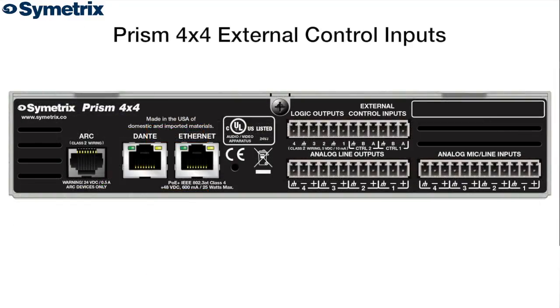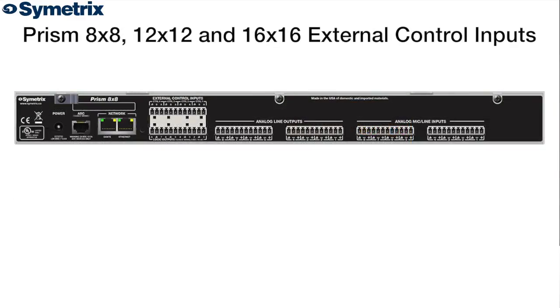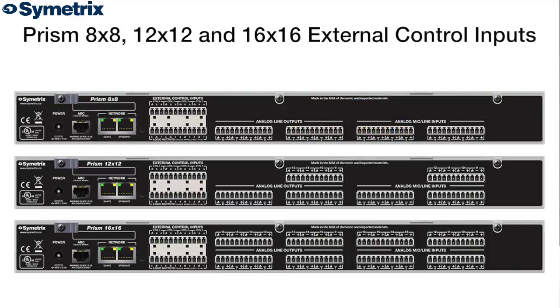Prism 4x4 has 2 analog control inputs that can be used either as 2 potentiometer inputs or 4 switch inputs. The Prism 8x8, 12x12, and 16x16 each have 4 analog external control inputs supporting 4 potentiometers or 8 switches.